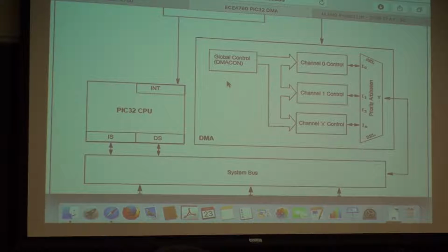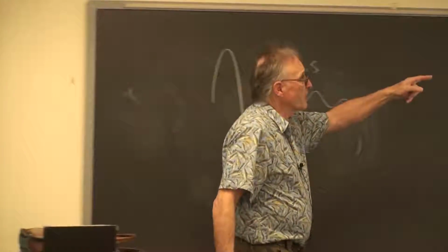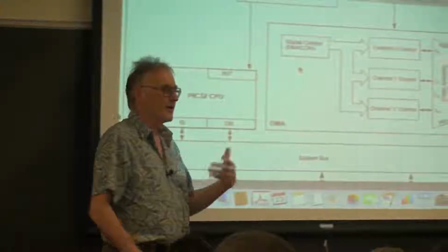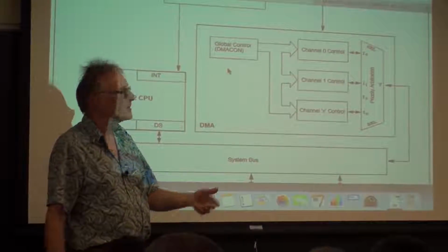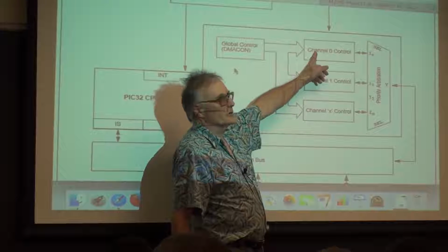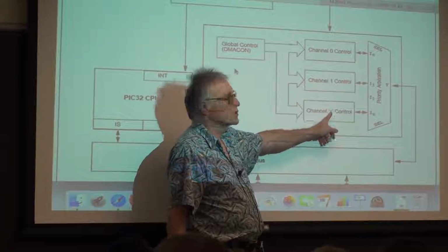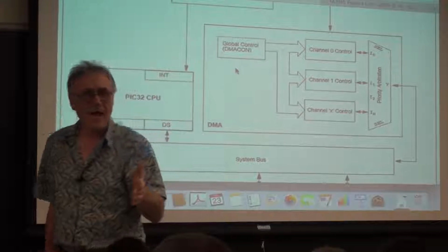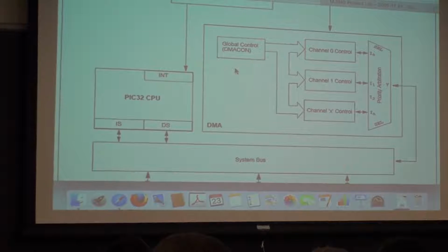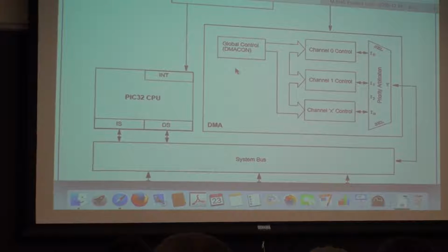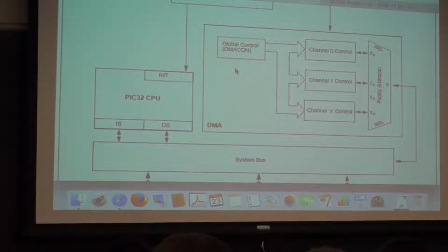Tamid and I wrote a program that used one DMA controller to run a television, which requires constant update, unlike a TFT screen. One channel to run the television, one channel to read the A to D converter, and another channel to feed the DAC, all using separate DMA channels, all happening logically at the same time, but in fact on the bus they're interleaved.